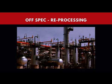The off-spec LPG will be routed back to the amine treating unit or Merox treating unit, and the H2S will be knocked off. But again this is going to take time and effort. When you are reprocessing, the plant throughput may have to be reduced, and a lot of effort is involved.